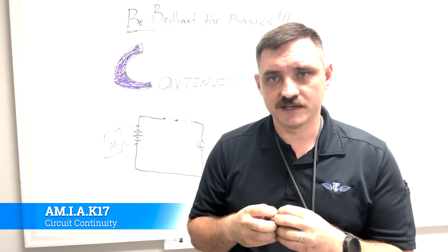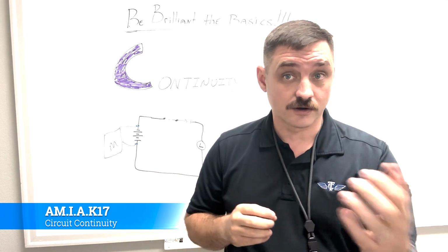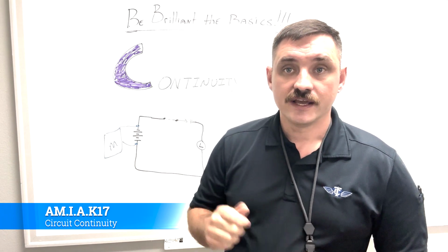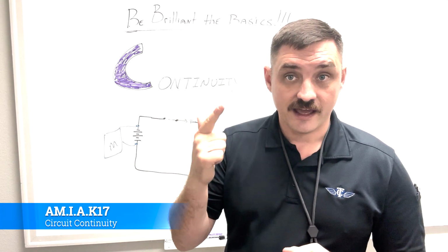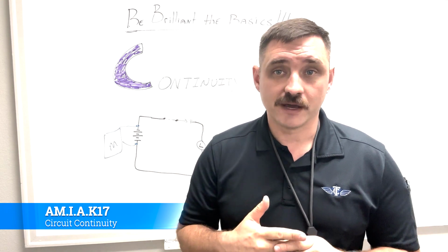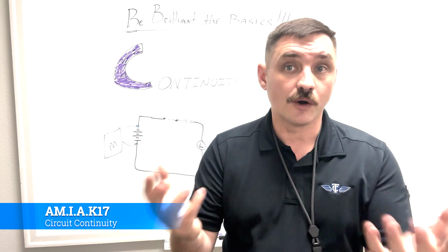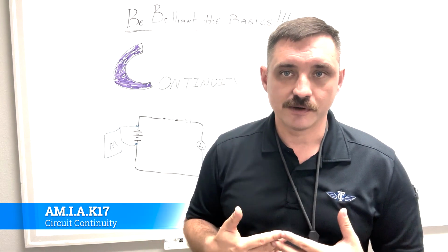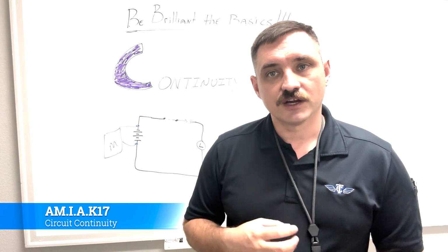Those elements come into the connector, and we're going to see in our corrosion class that one of the key things with corrosion is having electricity, having some sort of presence of water, some sort of medium, and differential metals. Those three things combined always create corrosion. We have all three of those things inside of a connector that's exposed to the elements, so you'll end up having a corroded connector.